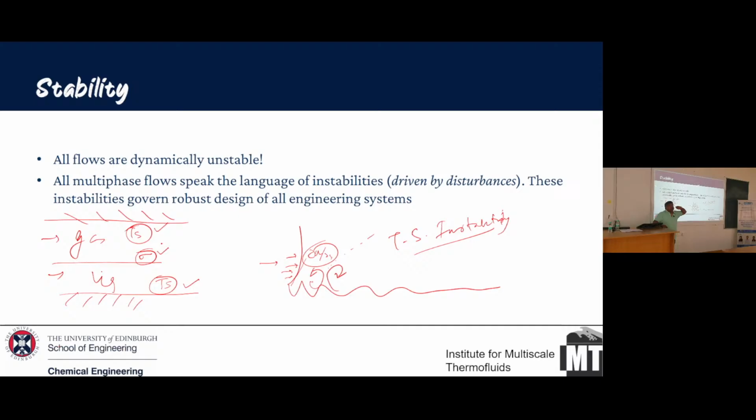If you have a completely stratified system, if you look at a flow probably at low gas and liquid flow rates, you might find that the interface has slight disturbances, but is ultimately nearly straight. It just means that instabilities are not very strong. But as you increase your gas flow rate, or your liquid flow rate, you'll see waves developing on the interface. Not because of the bulk mode in the gas phase or the liquid phase, it is the interfacial, the surface tension which is playing a role here.